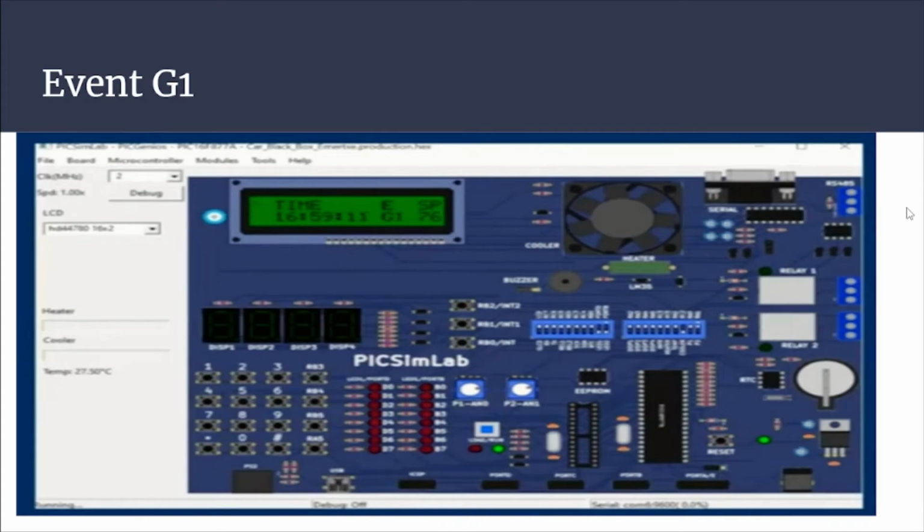These are all the event captures. Required events have to be captured and stored in the memory. Every event should have a format like event signature, event time, event speed. These events should be captured in real time no matter which mode you are in.